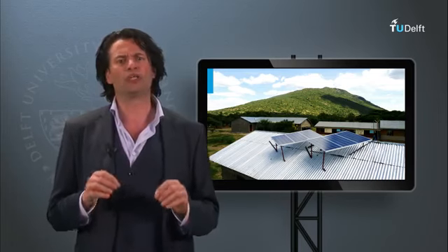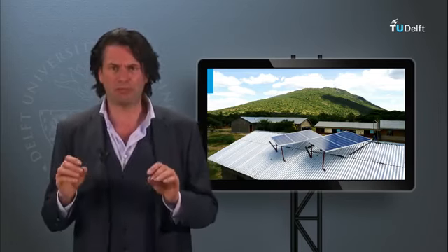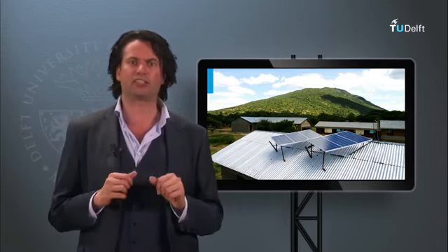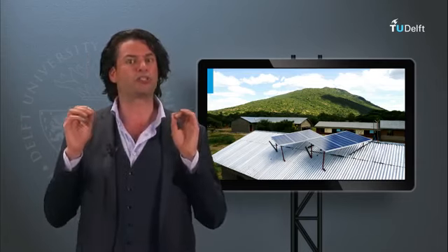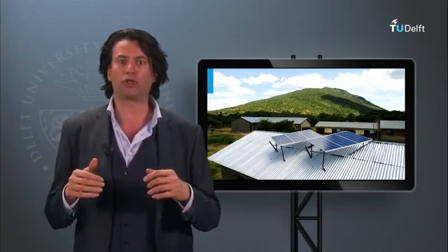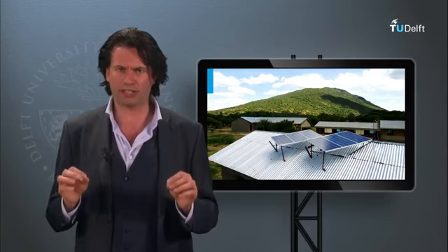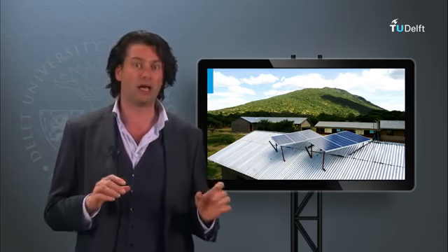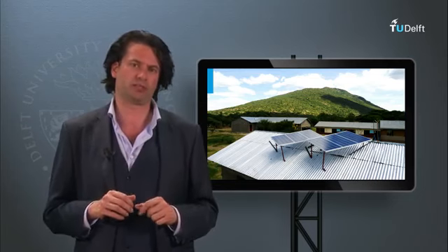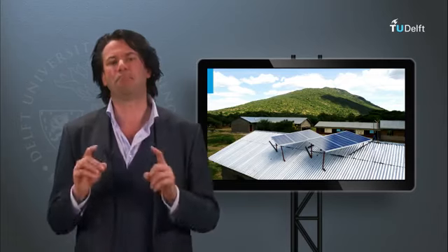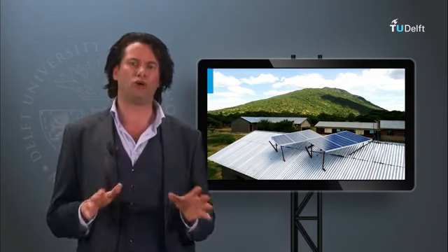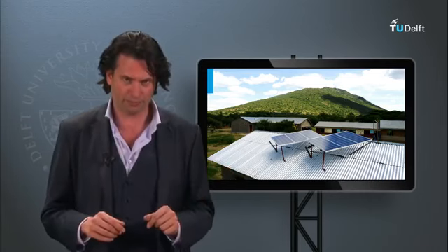For places with severe disparity between the summer and winter irradiances, the number of autonomous days would increase for winter and the system cost would consequently rise. Also, the component margins considered for various parameters could differ from place to place based on the system requirements. Nonetheless, this method is good enough to get a basic estimate of the stand-alone PV system sizing.